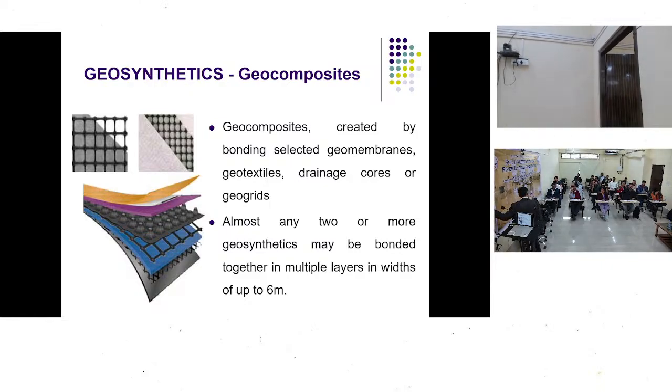from being punctured by any sharp edges of the stone masonry, which could puncture this geomembrane where water is flowing. Under the head of water, if you are having a 50-meter head of water, then at the bottom part of it, the 50-meter head of water will have a compressive force, and that compressive force can puncture the geomembrane. So, in order to protect this geomembrane from being punctured, a non-woven geotextile was installed.